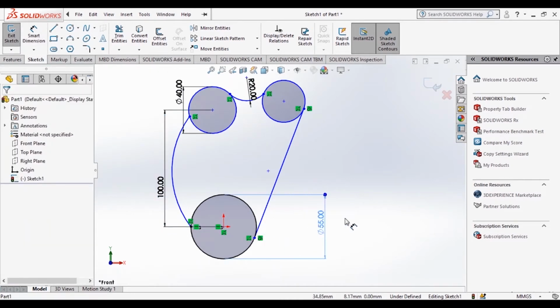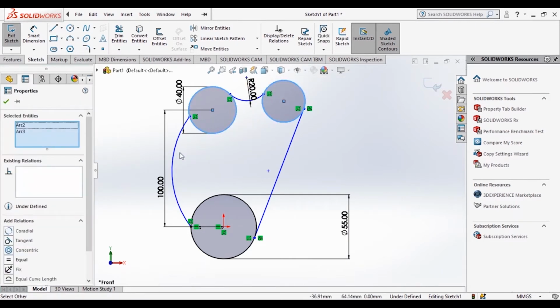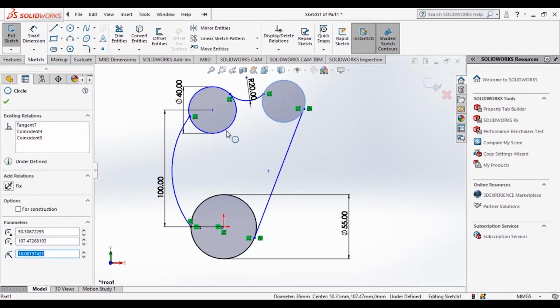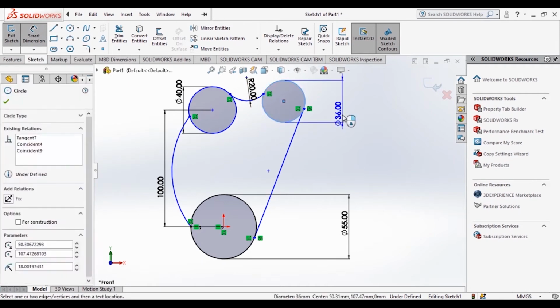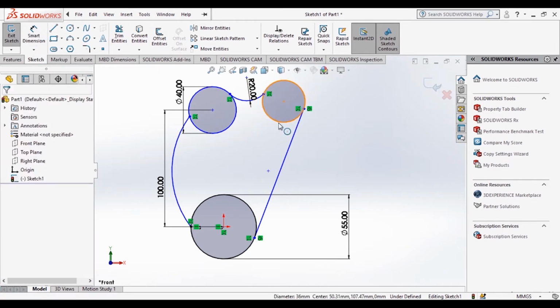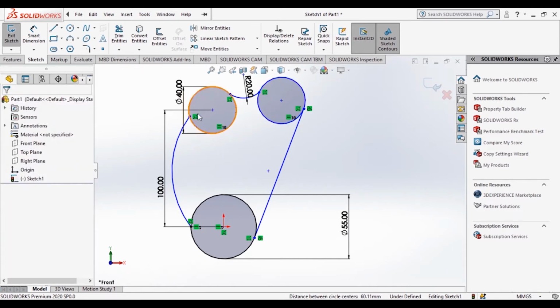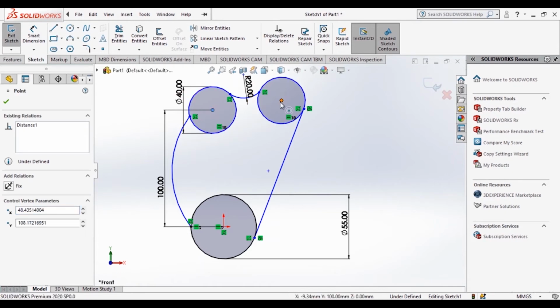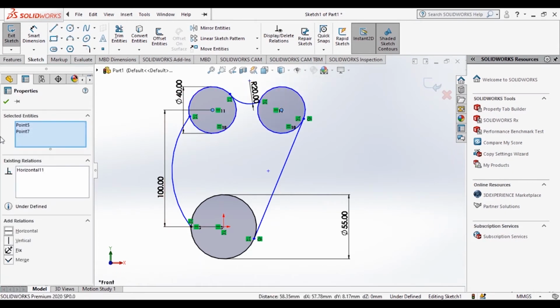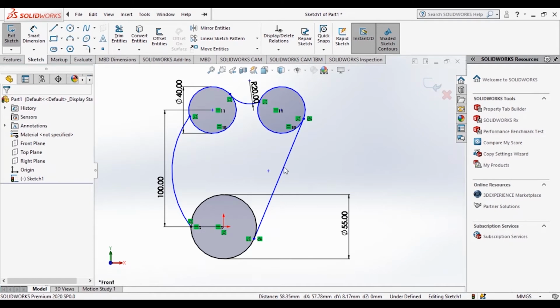You can find it a little bit different drawing because it is not fully properly constrained. And here you don't need to add this circle again, since it already has dimension 40. We'll just choose these two, add a relationship called equal, and make sure that both are equal in diameter, and these two should be horizontal, so I'll make it horizontal.